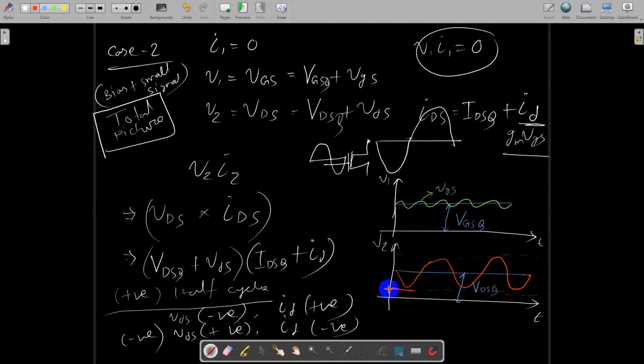This value is also positive because the MOSFET has to get that type of GM in saturation, and it has to maintain a headroom, a voltage margin that is greater than VDSAT, okay, the saturation voltage. So the MOSFET has to keep in saturation. So this voltage will always be positive, regardless of the swing of this node.